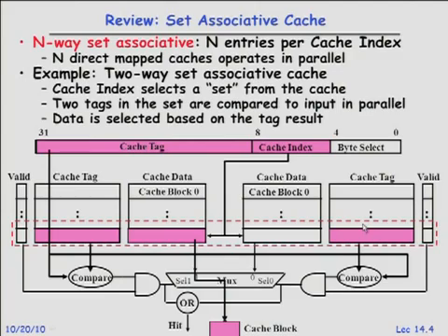Yeah. Does the cache tag that's stored along in each set, right, is that part of the cache size? No. Good question. So when we talk about the cache size, are we counting the tag? And the answer is no. So typically, when you talk about an 8K or 64K or 128K cache, you're only talking about the data, and the tag is like overhead, as far as that number is concerned. Okay. And notice, by the way, it's not that there's a tag per set. The dotted line is a set. It's actually a tag per possible entry. Okay. Good. Any other questions?